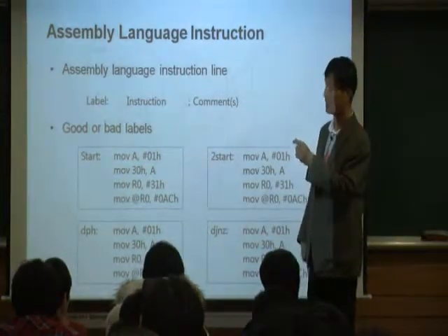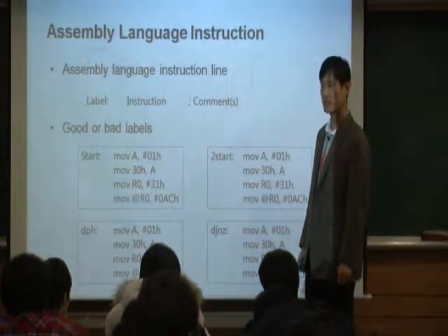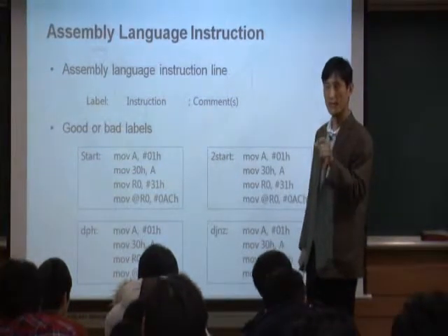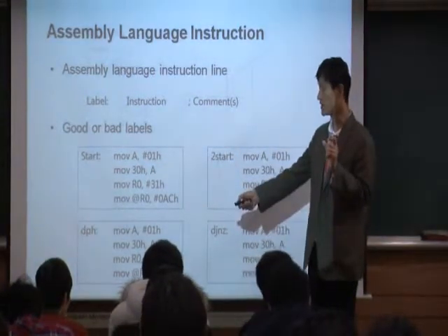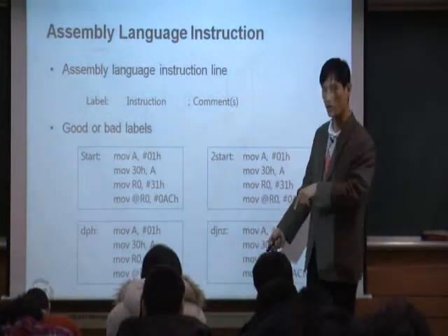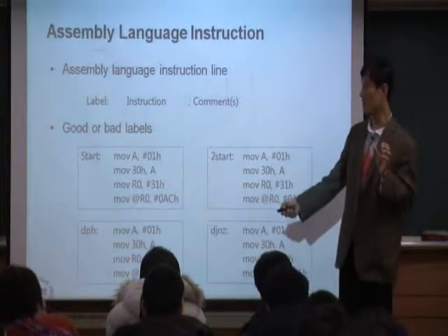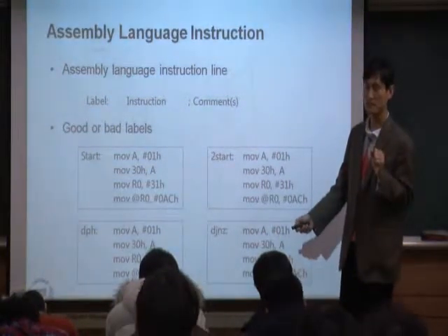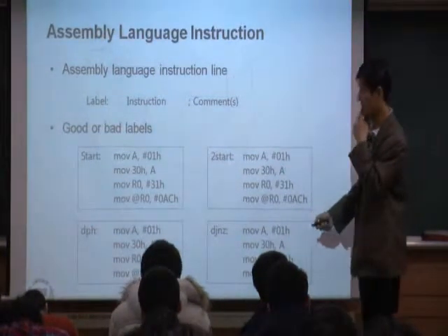If you look at maybe the second lecture, then you see a list of registers, right? Registers have their own names. DPH and DPL, DP means data pointer, right? Data pointer high, data pointer low, okay? There's DPH, DPL. Those names are already reserved for registers, therefore you should not use them, okay? Because this is specially reserved for registers.